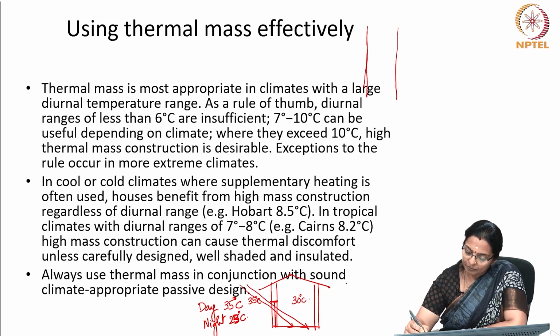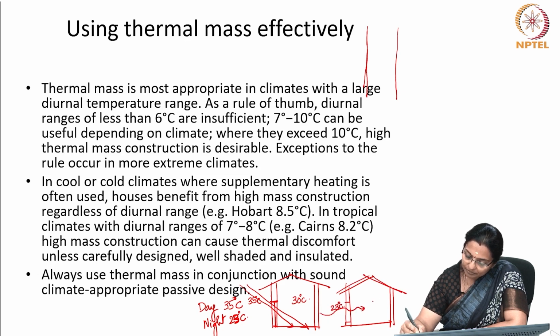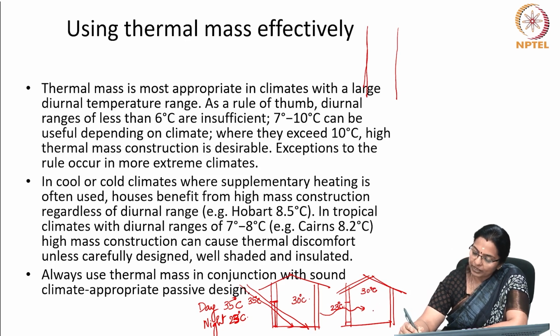At night, what will you do? You will open the windows and allow breeze which is at 23 degrees centigrade to enter inside a room which is 30 degrees centigrade. Now, what will it do? It will ensure that the indoor becomes, say, probably 27 degrees centigrade.